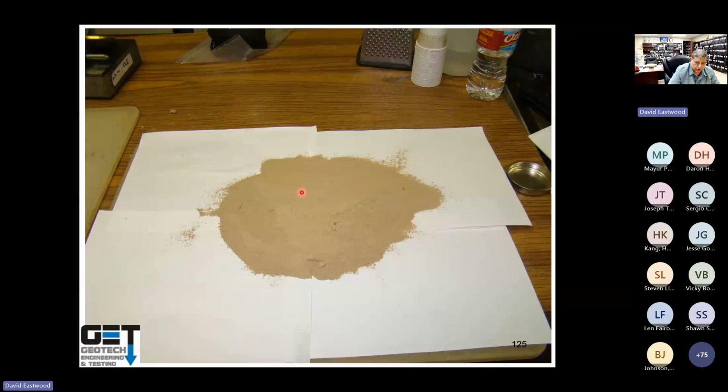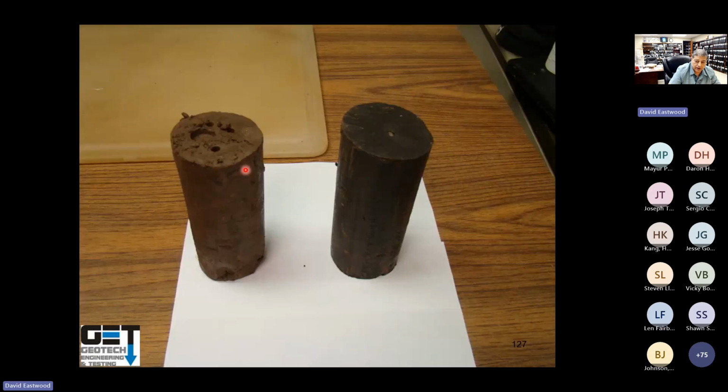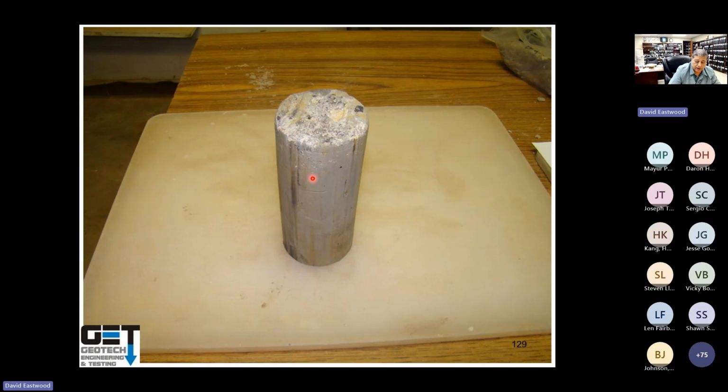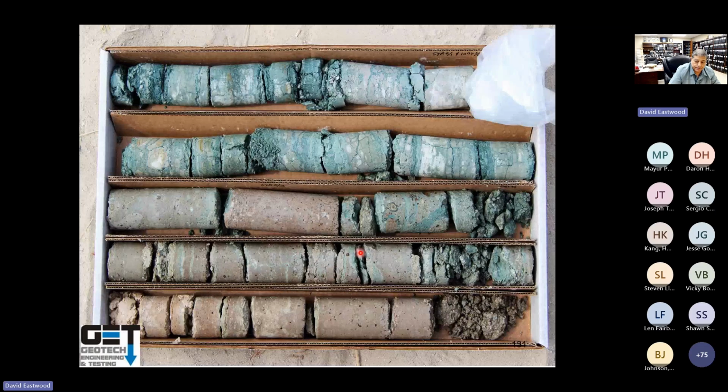You have silty soils that you see out there in the Woodlands area, the Bridgeland area. The grain size of the silt is bigger than clay, but smaller than sand. That's the silty soils, a really hard material to build a road on top of. You have to stabilize it and make sure you have good drainage. So we have clay soils, you go deeper, you get orange clay, you go deeper, you get white clay, you go deeper, you get into weathered rock. That's rock below that.